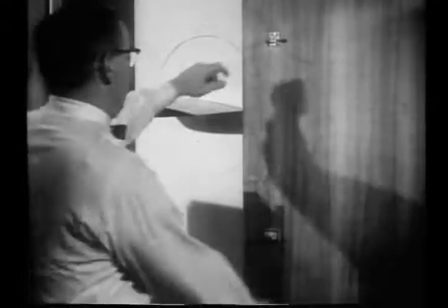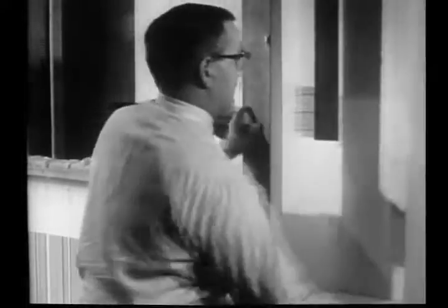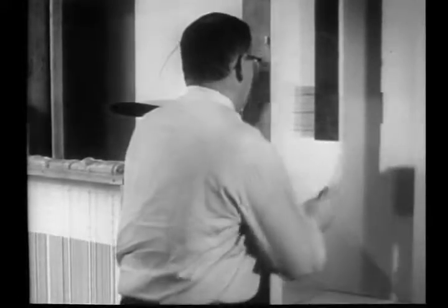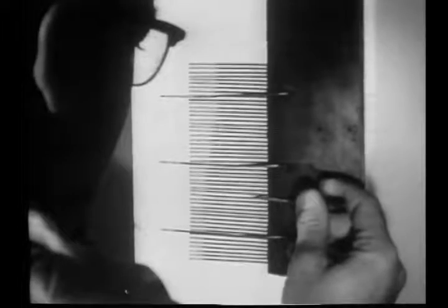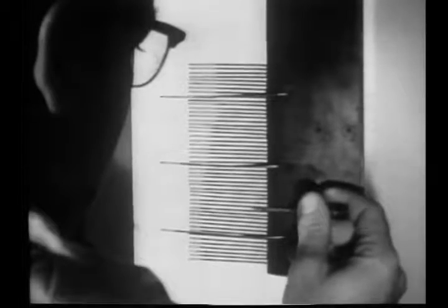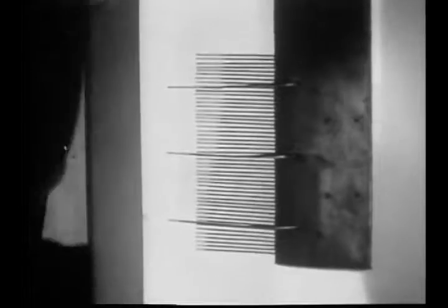Turbulent boundary layers thicken more rapidly and produce greater skin friction than laminar ones. Thus, reducing the extent of turbulent flow reduces the drag of the profile. We can verify this by measuring the loss of momentum in the wake of the airfoil, using an array of total head tubes. The tubes are located far enough behind the profile so that the static pressure in the wake is nearly the same as that in the main flow field.